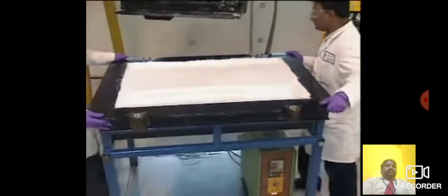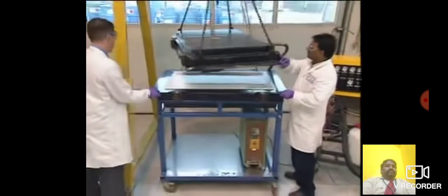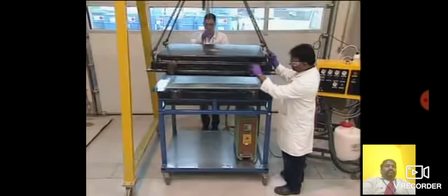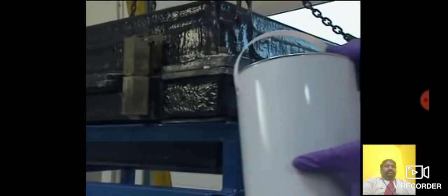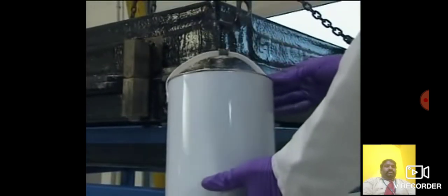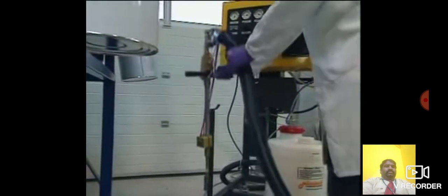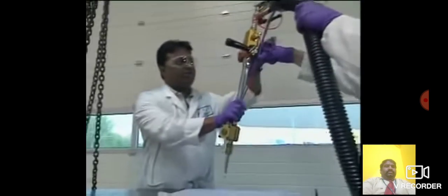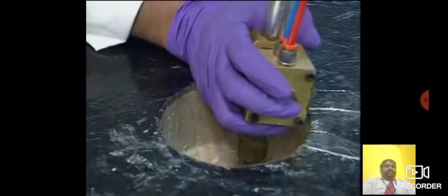The mold is closed and clamped using bolts, toggle clamps, or sometimes a press. Liquid heating is used to ensure consistent temperatures. 40 degrees C is a typical mold temperature. The mold is vented at the point of final fill. Resin is injected from a central point at typical injection pressures of between 2 and 4 bar.